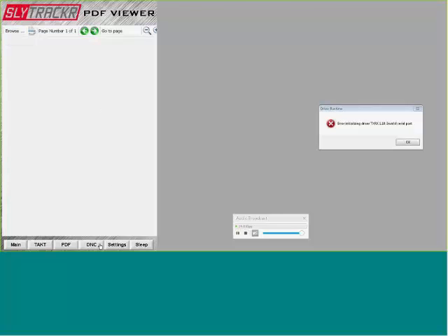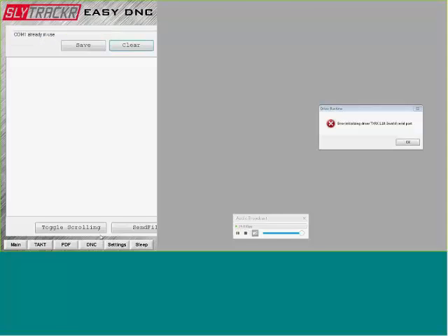Another .NET object that we've integrated in is a DNC. Again, kind of distorted. And DNC, for those of you who are not familiar, is how a shop would get their programs in G-code into the machine tool and out of the machine tool for that matter.